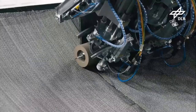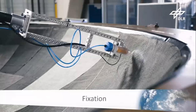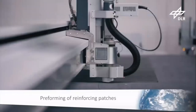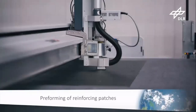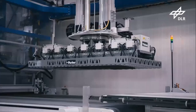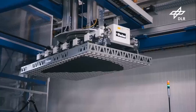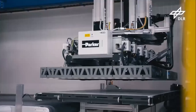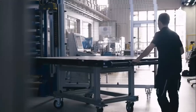The fixation of the plies is carried out by means of epoxy resin used for infiltration later on. This saves additional adhesive materials. The reinforcing patches are cut with an automated cutting machine, lifted by a gripper and placed on a movable transport table. Then the transfer to the robotic cell occurs.